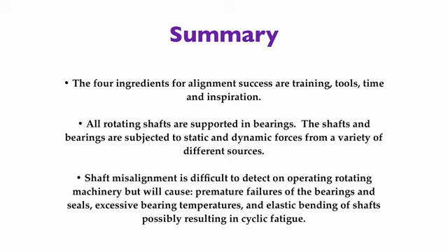We discussed that there is a possibility that the shafts of our drivers and the shafts of our driven machinery can be misaligned, and that the coupling that connects these shafts together attempts to accommodate a misalignment condition, but there is a limit to the amount of misalignment it can accept. Once that limit is approached or exceeded, the shafts begin to elastically bend. Determining what acceptable alignment tolerances are will be discussed in another tutorial.